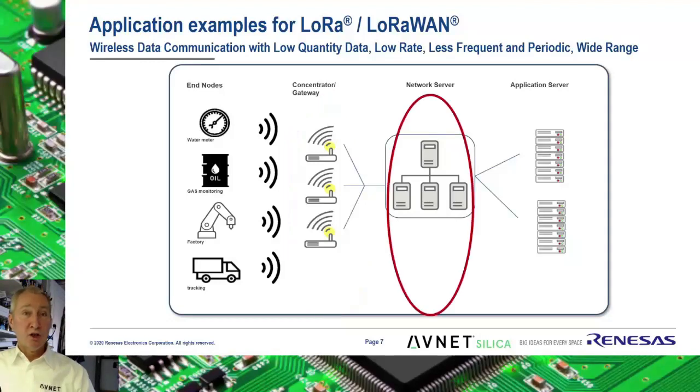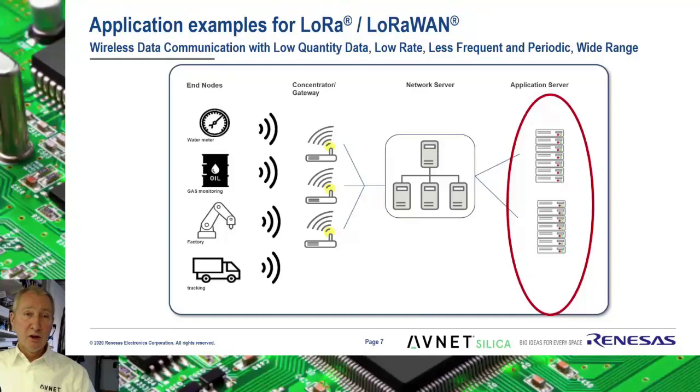The messages are subsequently received by the LNS where the node has been registered. This can be Loriot, KPN, The Things Network or any number of organizations. These can be either public or private. Finally, the LNS can forward the LoRa data to an application server to be visualized and processed. Such an application server can be, for instance, Cayenne, Azure Web Services, Node-RED or any other.